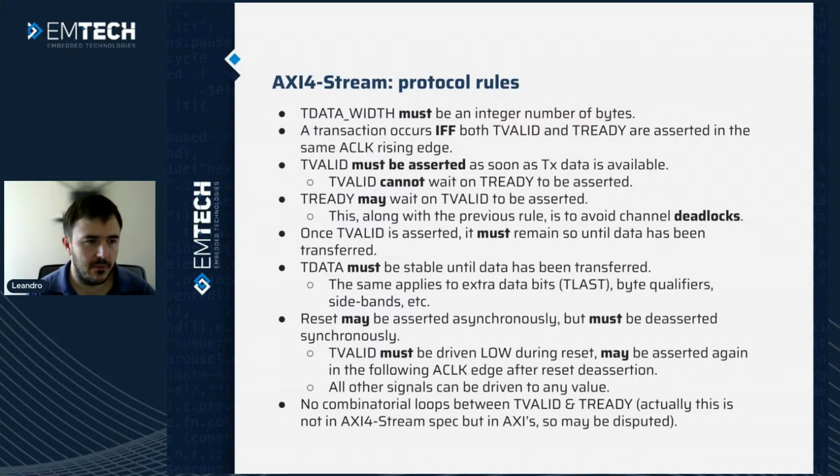There is a couple of rules about the reset. It's, well, very classical, I mean, this comes from ARM, so from ASIC design: asynchronous assertion, optional, but it must be deasserted synchronously. And TVALID must be driven low during the reset. It may be asserted again in the following rising clock edge after the deassertion. The other signals can be driven to anything. That's it. It doesn't matter.